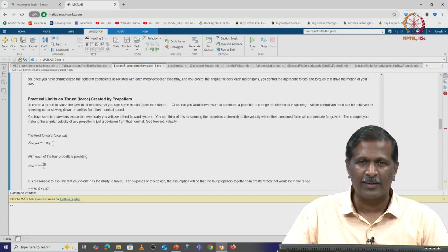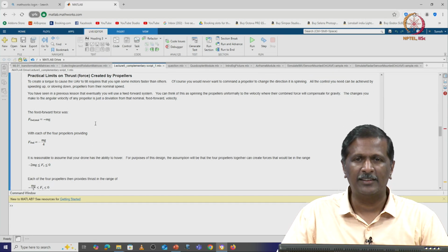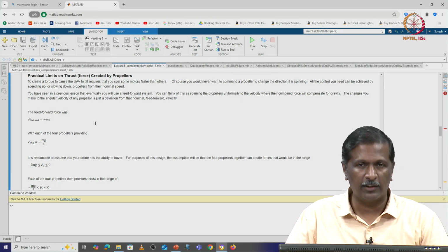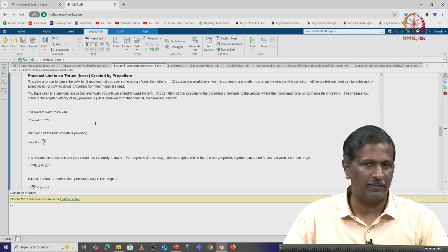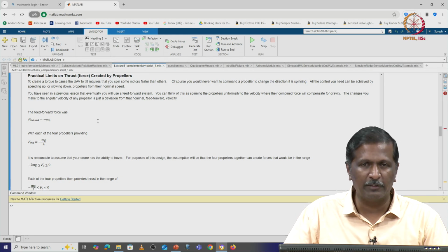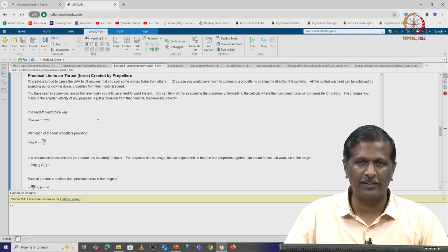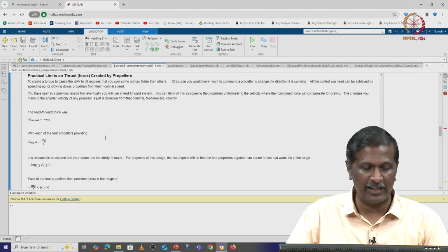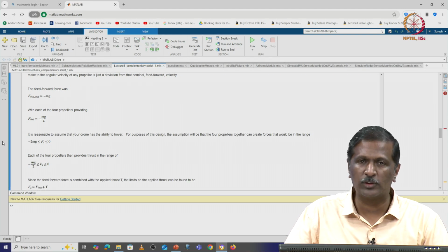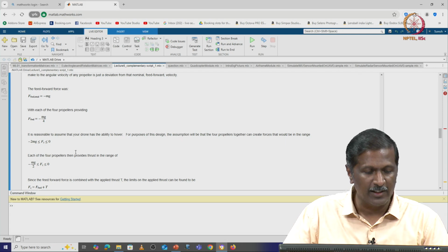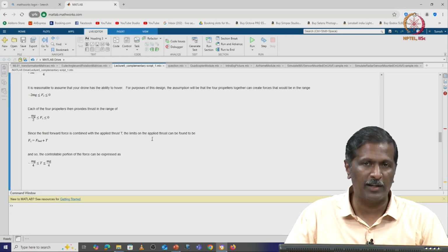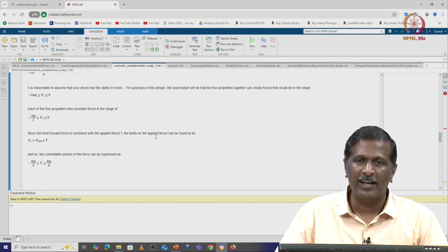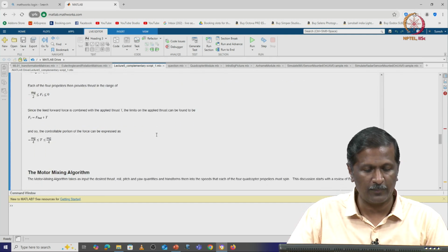So, what we do is take twice the total weight. So, at 50% throttle, I should be able to get thrust forces equal to the gravity force. Okay. So, you have the remaining 50% for operation of your vehicle, to move at a specific speed and so on. That is why we take that into account. So, we need to limit the force generated. We have to include that limit: what is the minimum value and the maximum value of thrust I can get. I have to limit them so that I can simulate it accurately, right.